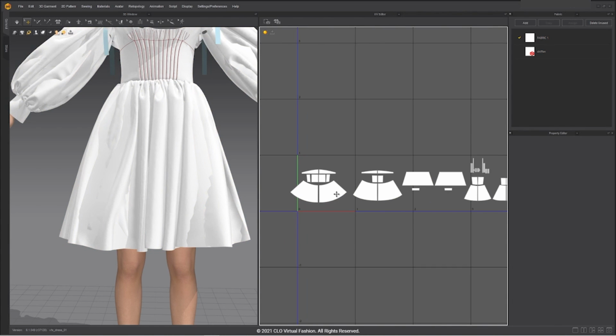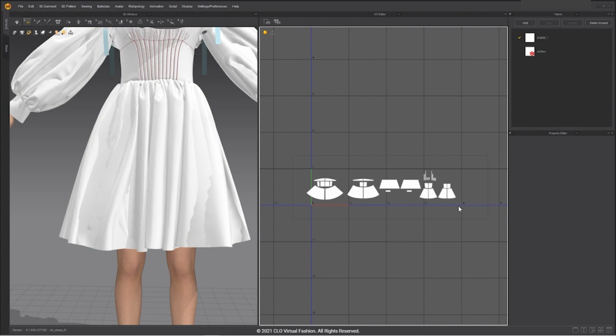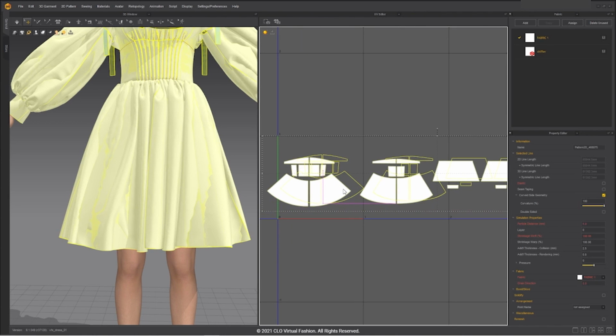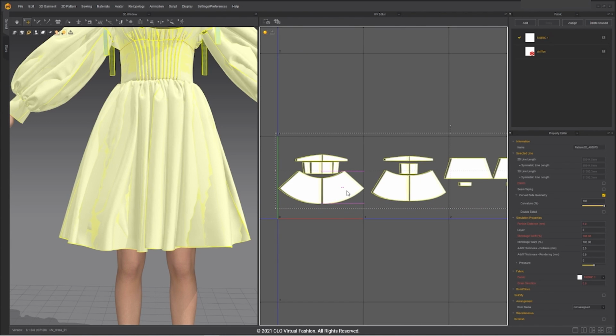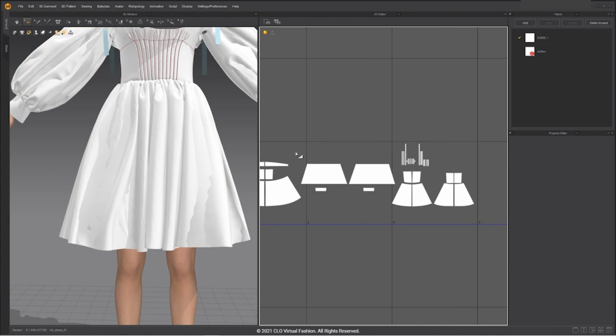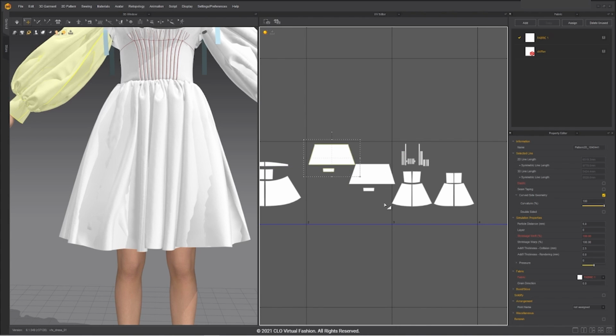When arranging UVs, you must always scale uniformly. This is to ensure that later when you texture, the scale is not inconsistent when you assign the same material to different shells. Please make sure to optimize the 0 to 1 space as much as possible, meaning fill up the tiles with your shells without leaving too much empty space. This is so that you can get the most amount of resolution when texturing.